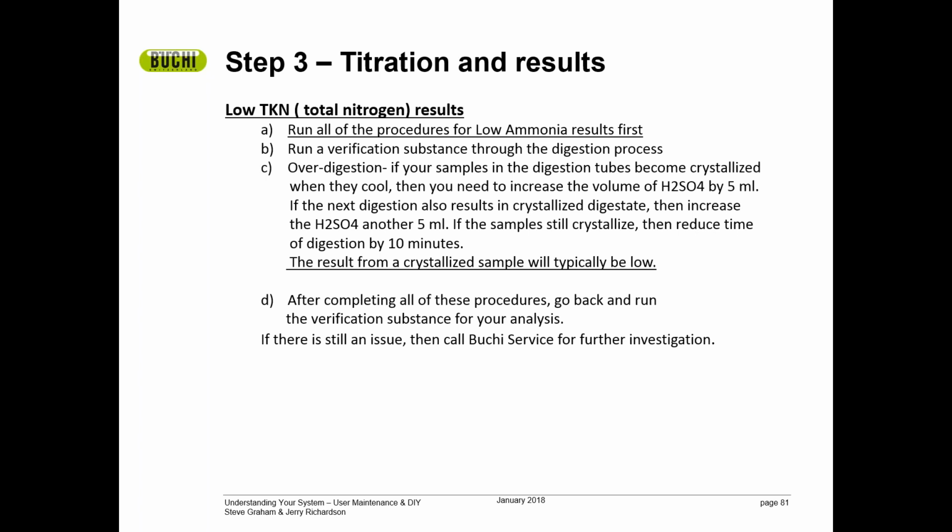Just like low ammonia, you may have low TKN results. Obviously, if your ammonia on your distillation system is running just fine, but your TKN results run low, there's a problem with your digestion.